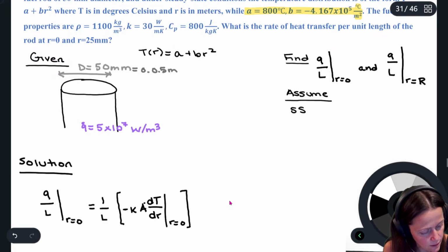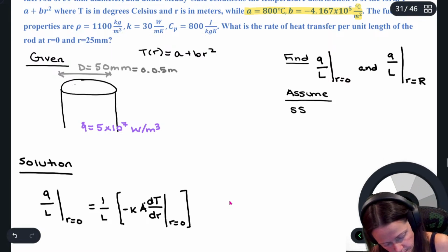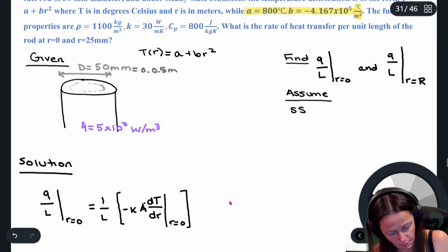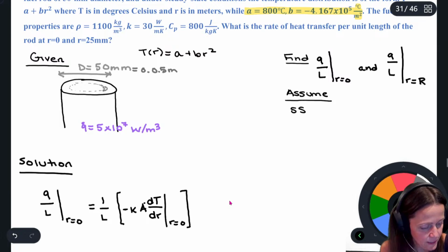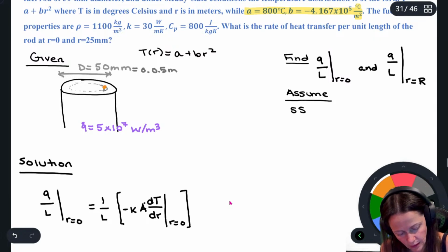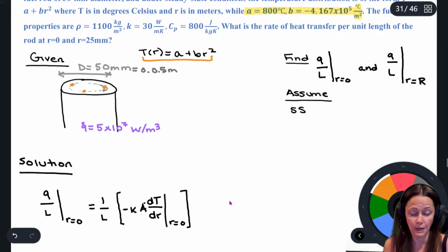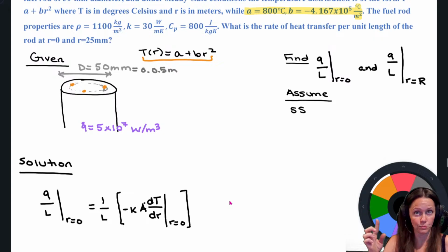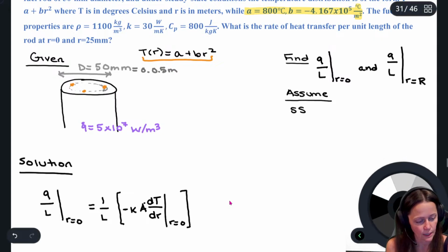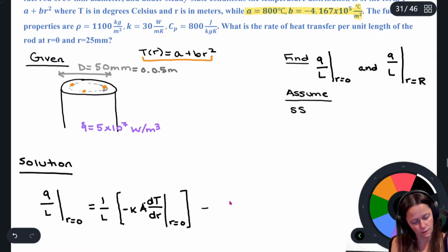So let's say this is all at the same R. It doesn't matter whether I'm looking right here or here or here. If I plug in that R value, I'm going to have the same temperature. And so that temperature distribution is symmetrical all the way around. And so, well, this guy is just going to be 0. How come? Because thermal symmetry.